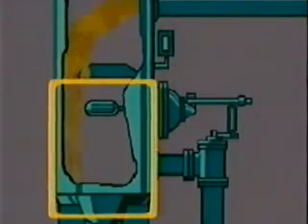Liquids and solids collect in the liquid accumulation section. Since this section is effectively isolated from the stream turbulence, gravity pulls on the heavy, dense solids such as sand and clay, settling them on the separator bottom. These solids are routinely removed during periodic maintenance.